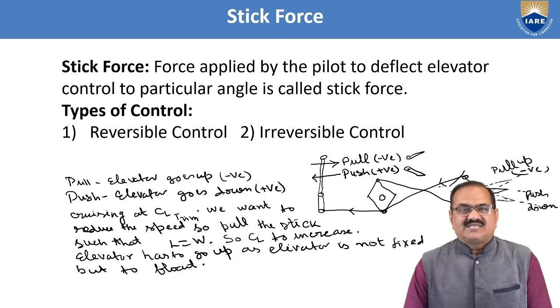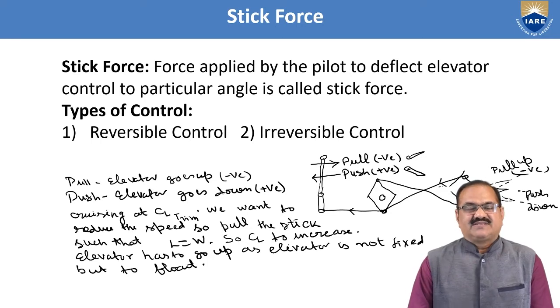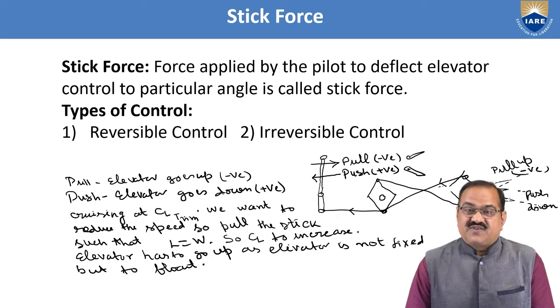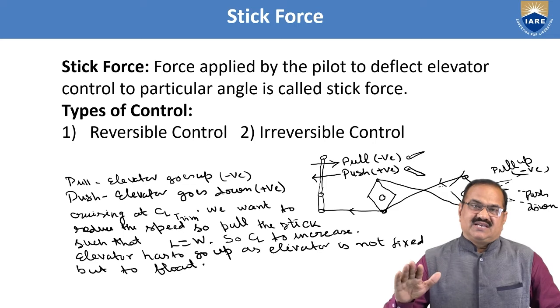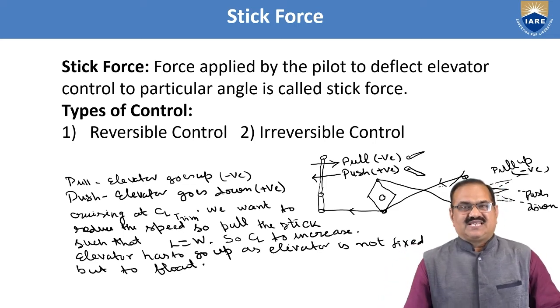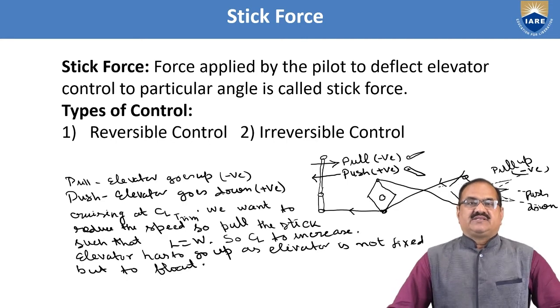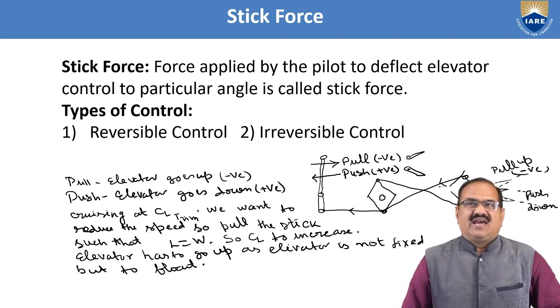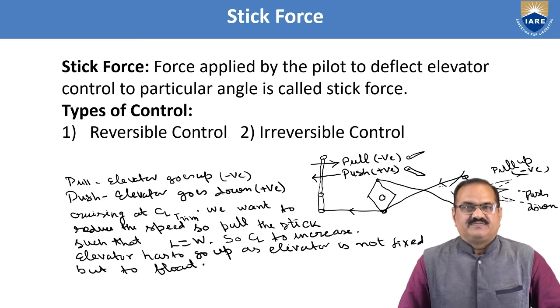Till now we have not discussed any force which is experienced by the pilot. We are only concerned with stick fixed condition, where a constant angle of attack of the control surfaces is fixed. They are not floating. In the previous class, I discussed the floating also. And today, I am going to discuss the stick forces and how these forces are applicable.